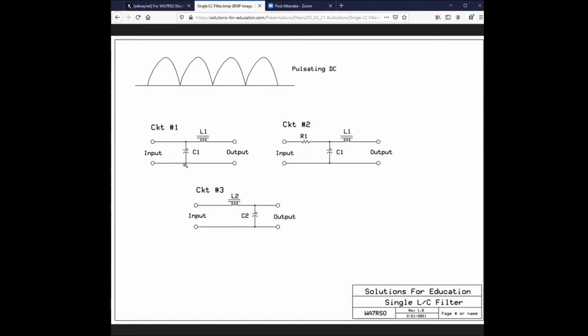Remember what I told you? This guy here is a dead short. And as a dead short, it can draw lots of current. So you put in a bigger fuse, not knowing any better, and you turn it back on. And this time you wind up smoking the diodes. Oh, well, maybe I should do something different. Guess why they do this? They put a resistor in series with this so as to dampen the surge, and that's called a surge resistor. So they do this to reduce the surge.